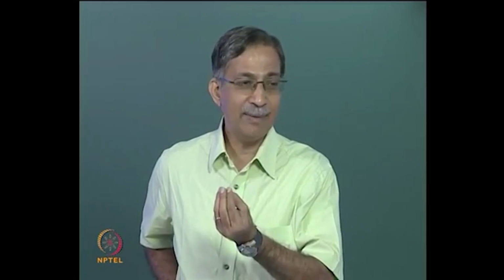But my question to you is about that 40 kilonewton answer that you got. Will you get a different answer once the joint is rigid? How much will it change? It will not change. Some change must be there between a rigid joint and a hinged one. Please note, it will not change if you assume axial deformations are negligible. If you assume axial deformations are negligible, you are dealing with a funicular structure. There will be no bending, no shear force. It's not possible. It's a funicular arrangement. Whether the joint is rigid or hinged makes little difference.